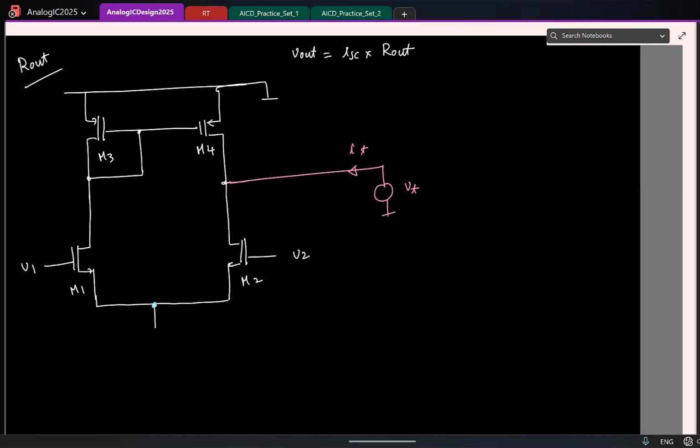So I can find the effective resistance looking down and the resistance looking up. I'll try to do it explicitly. For finding that, the way to think is the following. Instead of applying one voltage at this node, I can assume that this node is split. Basically, I'll assume that I have one voltage Vt connected here and another voltage Vt connected there.